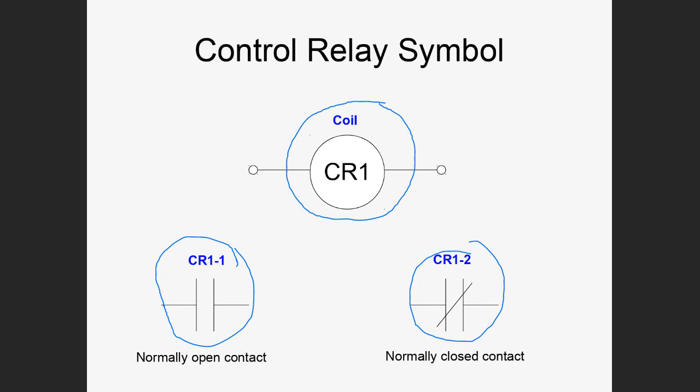Well, relays are still used for switching devices. As you may be aware, you can connect some devices directly to the output of a PLC, maybe a lamp, some kind of low current device. But what if the PLC is controlling a motor, like the garage door program that you worked on? Or maybe even something heavier than that. What if it's controlling the elevator motor, or something that pulls a lot of current? How would you connect that to the PLC?